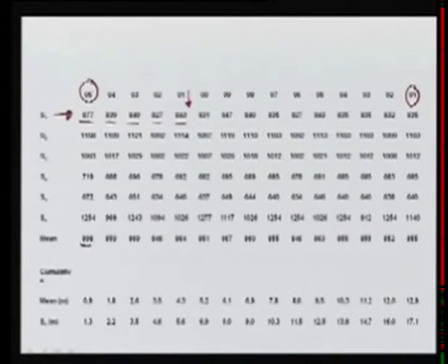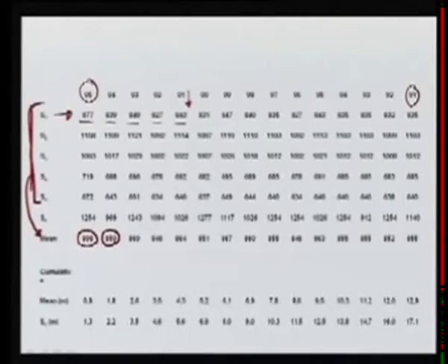Using this data, we can find out the mean of 5 stations, because at S6 we want to check the consistency. S6 was moved in 1990, so we are not sure whether the data is consistent or not. So we want to check consistency of S6 comparing it with the mean of the other 5 stations. So that's why for S1, S2, S3, S4, S5 we can take the annual mean. So this gives us mean annual precipitation at the 5 neighboring gauges.